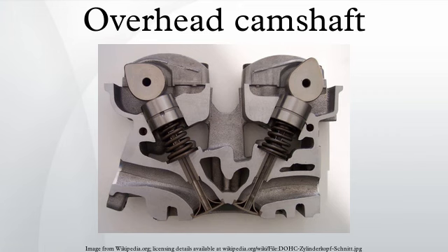The fundamental reason for the OHC valvetrain is that it offers an increase in the engine's ability to exchange induction and exhaust gases. Another performance advantage is gained as a result of the better optimized port configurations made possible with overhead camshaft designs. With no intrusive pushrods, the overhead camshaft cylinder head design can use straighter ports of more advantageous cross-section and length. The OHC design allows for higher engine speeds, which in turn will increase power output for a